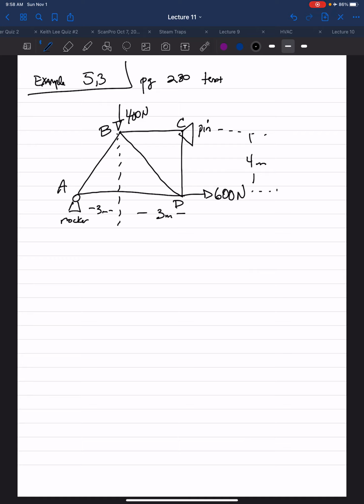And then at joint C, which is a pin, we have the CX and CY components of the support reaction and the forces in members BC and CD. So 4 unknowns there. Our rule is 1 known and at most 2 unknowns, but none of these joints fit.